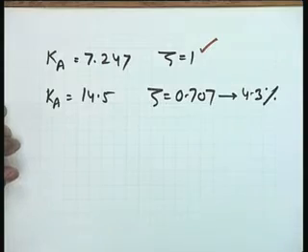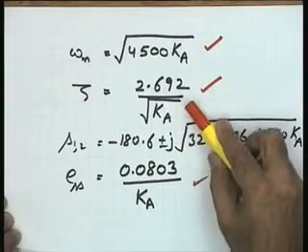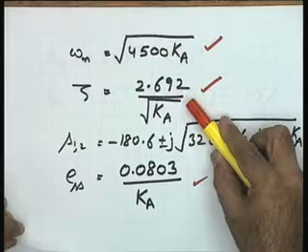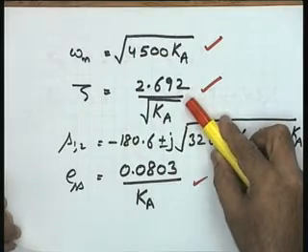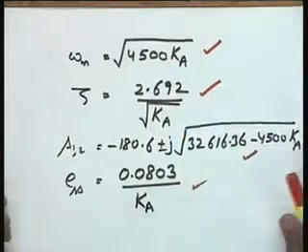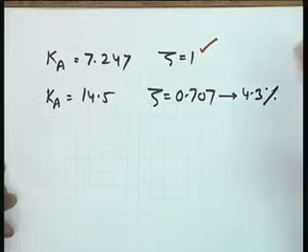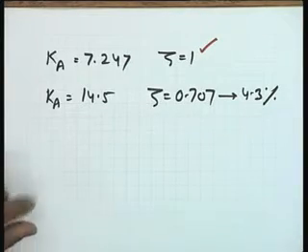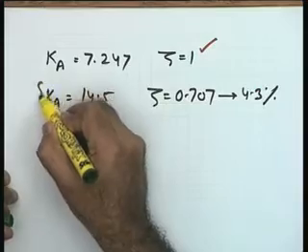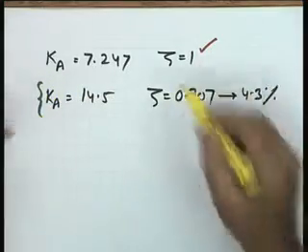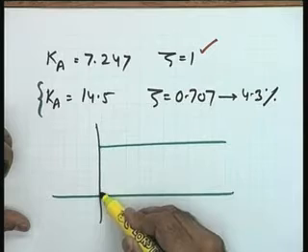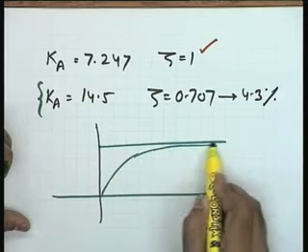So you see that I have used this expression only to get the value of Ka I am giving you. Don't worry about the numerical calculations at this stage. Look at the concept. I have taken a value of Ka so that zeta equal to 1, a critically damped case. Corresponding to this zeta equal to 1, look at the response I am going to get. The response for the standard second order system, I am going to get this.